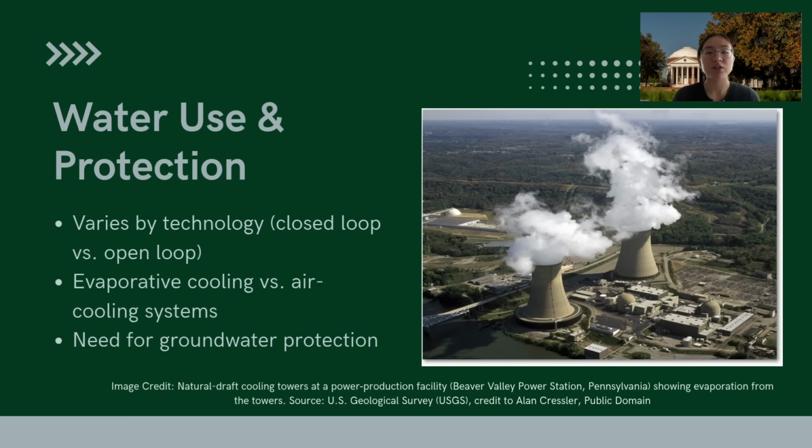A critical aspect of any geothermal project is groundwater protection. Wells are constructed with multiple layers of steel casing and cement to isolate the geothermal fluids and prevent any contamination of shallow freshwater aquifers.